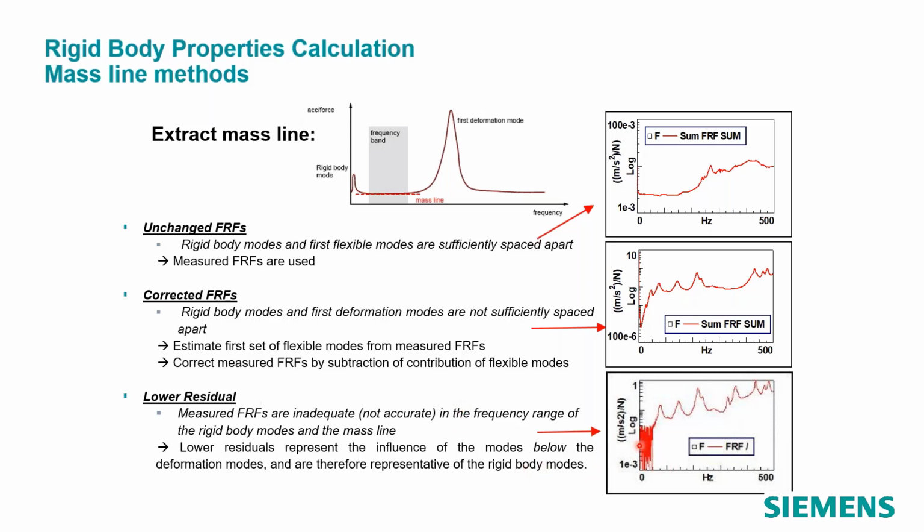And here you can see it's very noisy. I don't have much faith in these low frequency measurements at all. So I'm going to use a lower residual term instead. Here in the second one, I do have good measurements of the low frequency. I just have to compensate and remove the effects of the first flexible modes.